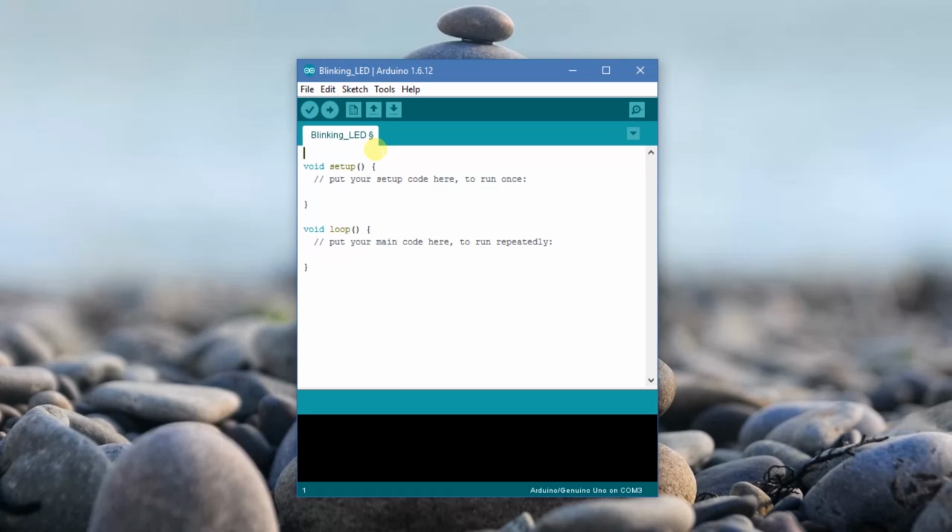In part 1, we declare all the global variables that we need and anything that we need to declare before we program the Arduino. In the setup function, we tell the Arduino how it's going to use those we have defined earlier.